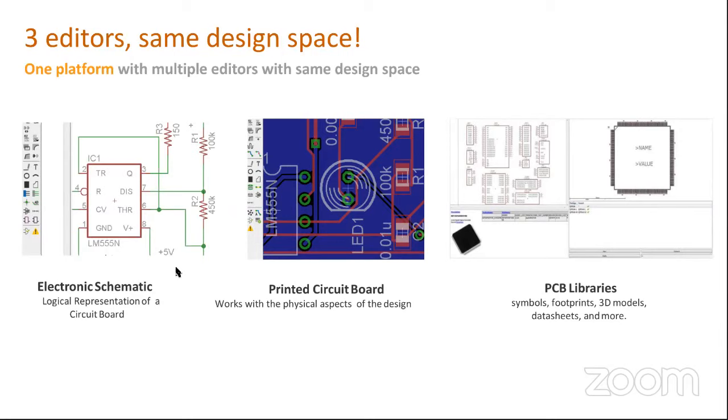Today, we're going to be covering the circuit board. We're going to be working with the physical aspects of the circuit board. Here, we're going to actually be working with the components that you'll be using for your design in a physical realm. And then the other platform that we have is called PCB libraries. The PCB library platform has multiple workspaces in which you can create your components. There's a symbol editor, there's a package editor, and there's a footprint editor, and then you put it all together in something called a device. We'll be covering webinars based on the library later on next month.